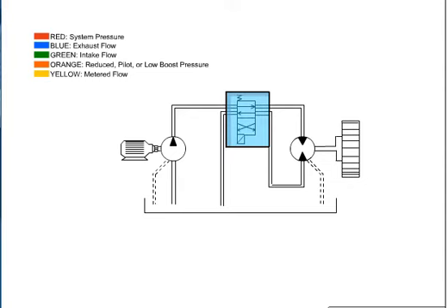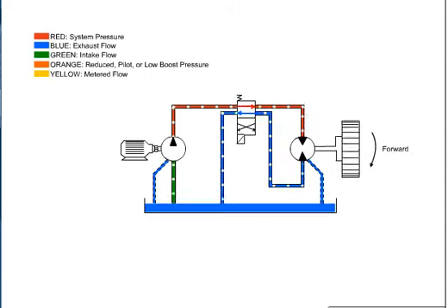In this circuit, a directional control valve is added to the circuit, and a bidirectional hydraulic motor replaces the hydraulic motor. The directional control valve will allow the hydraulic motor to reverse direction when shifted.